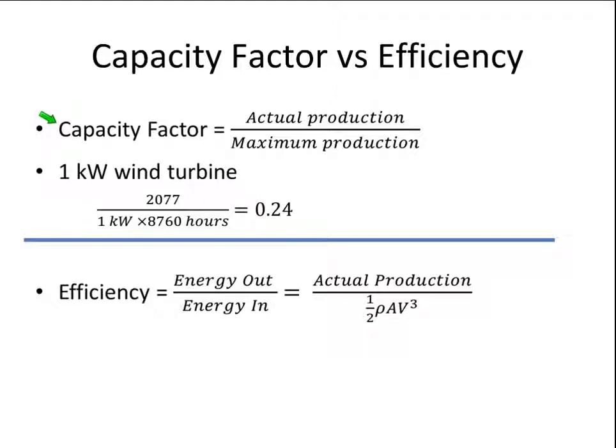If you broke down, that's going to make you run less of the year, thus you're going to have a lower capacity factor. We're seeing some of the new wind farms that are put up in Nebraska in some very good locations in their first part of the year that they're running have capacity factors in the 60% range, which is phenomenal. And part of that is they're brand new, so they're not breaking down, they're functioning very well, but also they're being put in a place that has very high and consistent wind speeds.